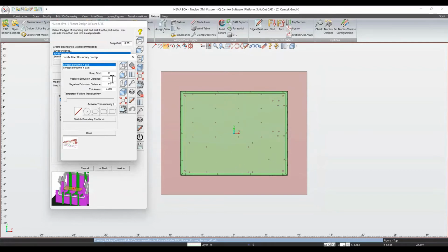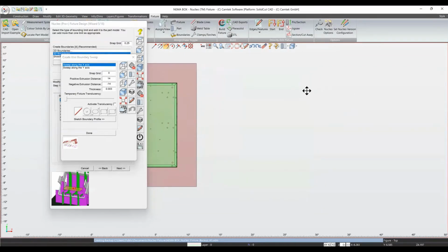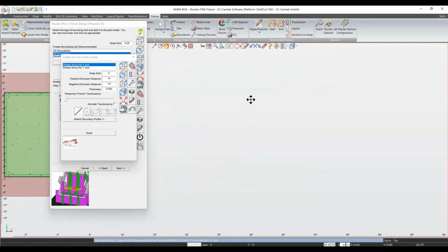So if that is the only axis that we are going to be drawing on, and we just want to extrude the sheet each direction, we need to make sure that the values entered in here are large enough to encompass the box and any extensions past that a blade might be sticking out. We can use the rulers on the screen here to look at how big this box is. Looking over here to the left, this box is approximately 14 inches wide.